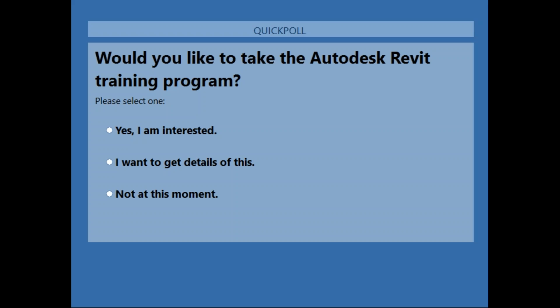The way that I showed you now, using filters to place any particular hatch or any particular fill color coding, I'm not going to say is the best professional way, but it's actually a more automatic way to do it. Because if I go now to any other level and create a wall with the fire rating already set up, I don't have to worry about the graphic part. I don't have to go and graphically create a hatch pattern for every single wall, because the wall will already have those in the filters.